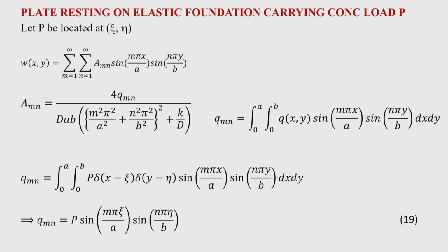So, let us see another case where the rectangular plate is resting on elastic foundation, but instead of uniformly distributed load it carries a concentrated load. Okay. So, concentrated load is a discrete quantity and therefore, the loading function becomes discontinuous. Because of discontinuity the loading function is not differentiable. So, that is the problem.